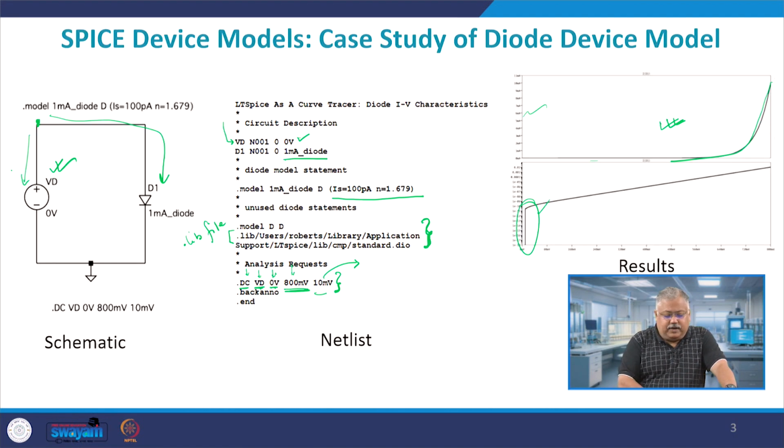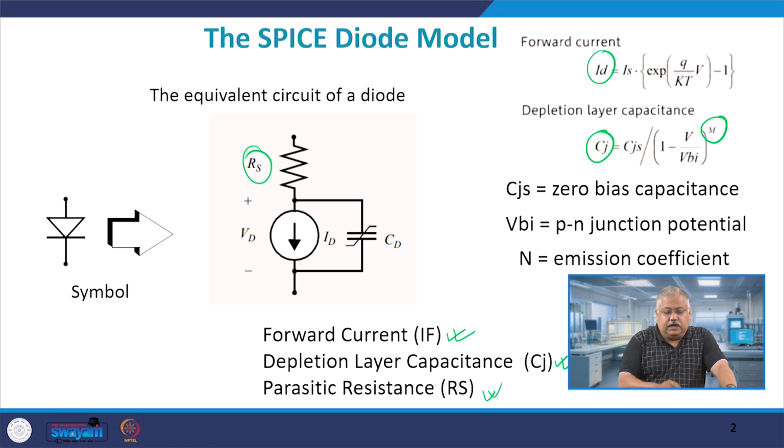Till now, when we were doing this diode analysis or even this equivalent circuit model, I was never telling you that the diode will be connected to an external wire by a contact. This contact will have some resistance, and this contact resistance will add to this value of Rs, thereby lowering the current. So the current which you are predicting in a SPICE model, let us suppose a very low level SPICE model, you will be over predicting the value of the current, whereas the actual value of the current will be relatively small in that case.